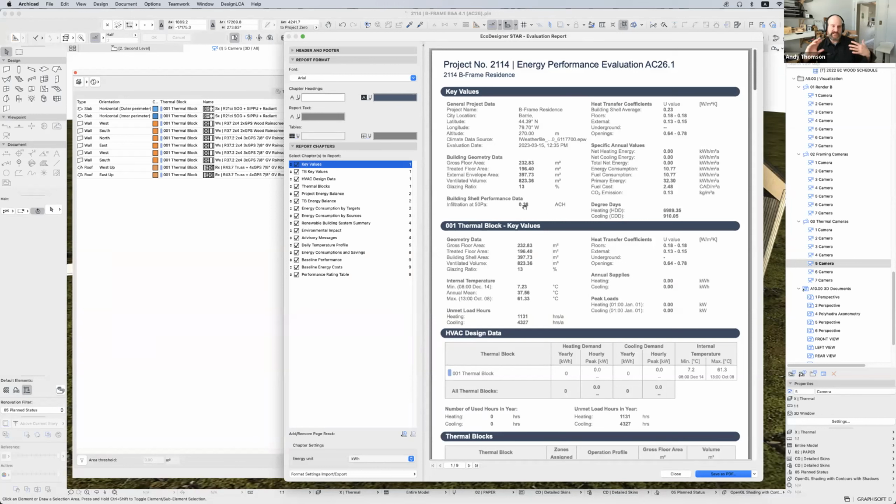on our buildings, because we make the detailing really simple, where it's easy for the trades to get a nice clean membrane wrapping the whole building with very few penetrations. And then when you run that door fan test, you're going to get numbers that are targeting Passive House at 0.6 or lower. 1.5 is still pretty good though.